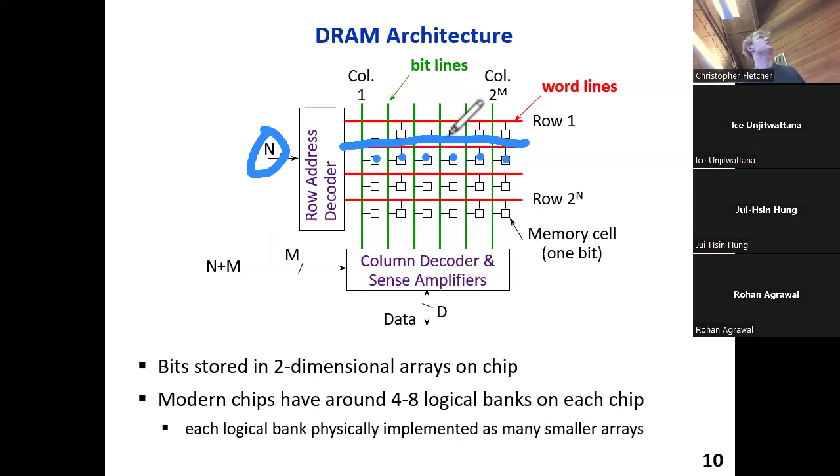Okay, so this is how you get bits out of a DRAM. And remember, when this operation happens, you activate the word line. That's going to charge all the bit lines in the array. All the values come out. You're going to write back all the values again because reads are destructive. Then the value that you originally read out is going to be passed through the column decoder.